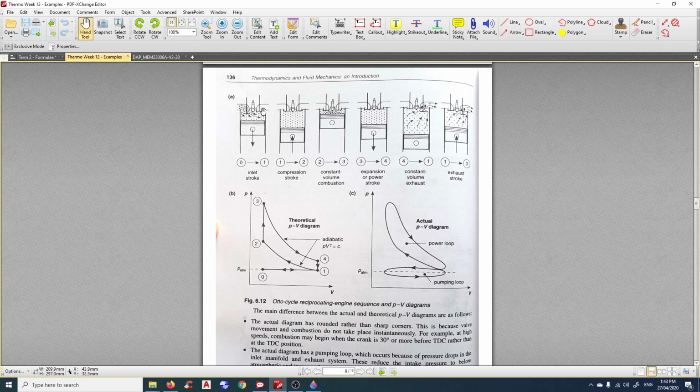If you don't replace the piston ring, you can see white smoke coming out from the exhaust, and over time the cylinder also does not stay smooth anymore, it becomes scratched, and we lose the vacuum, so we have to clean the cylinder and make it smooth again. That involves a lot of work, bringing the engine down.